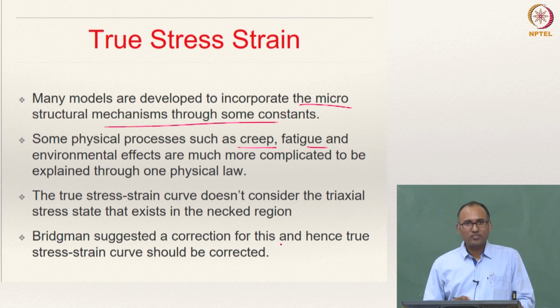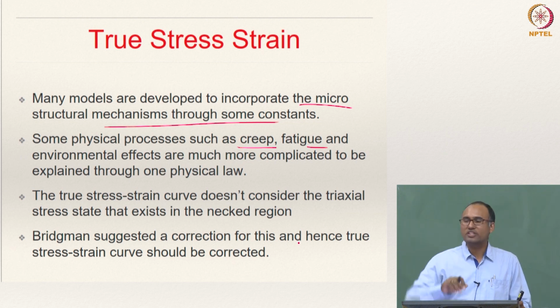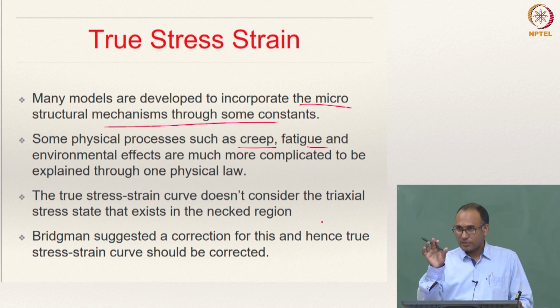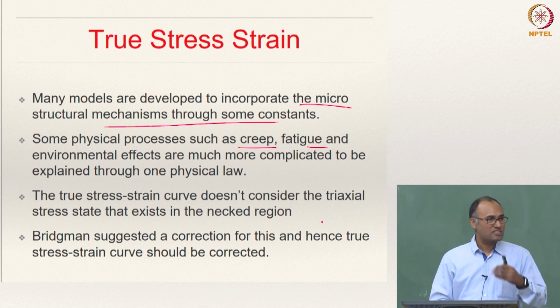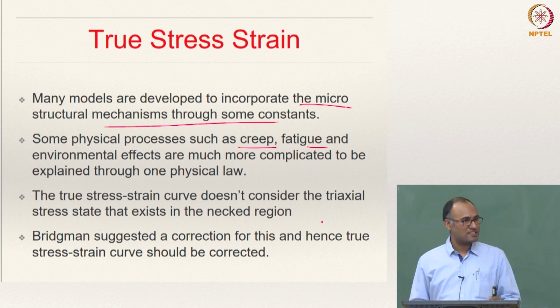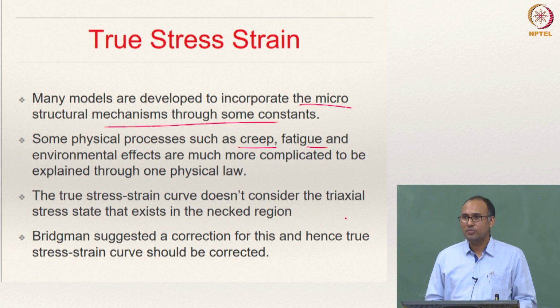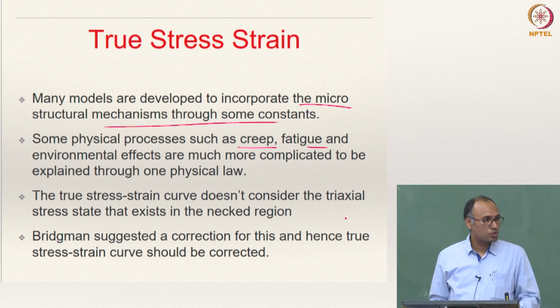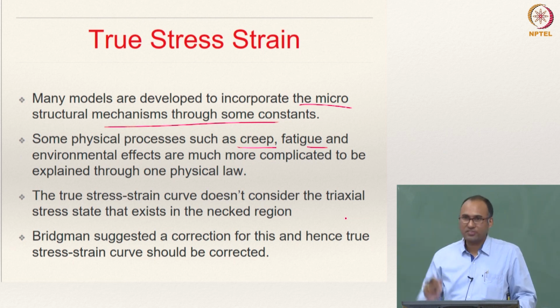and as we have discussed, the true stress strain curve does not consider the triaxial stress state that exists in the necking region. It does not take this into account. That means there is a local hydrostatic stress present during necking, and that is not usually taken into consideration when you draw the true stress strain curve, but it has to be considered.